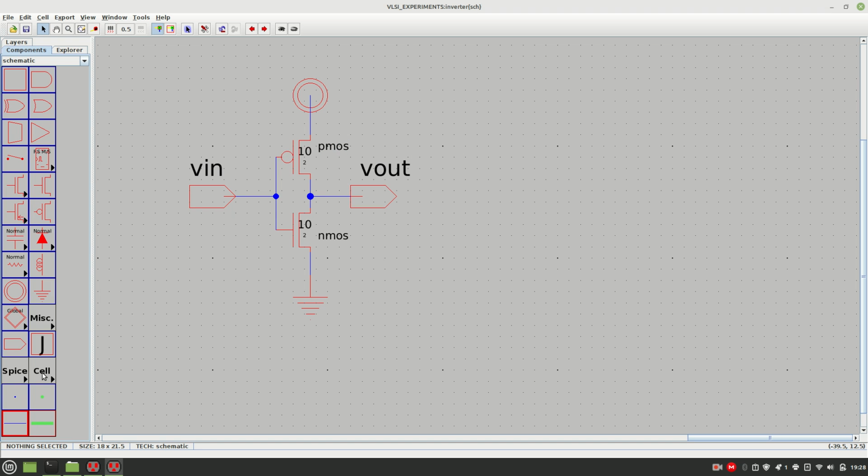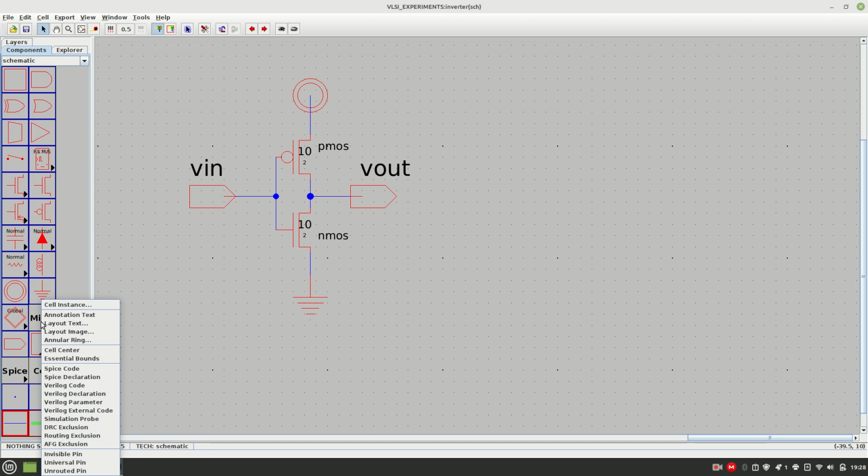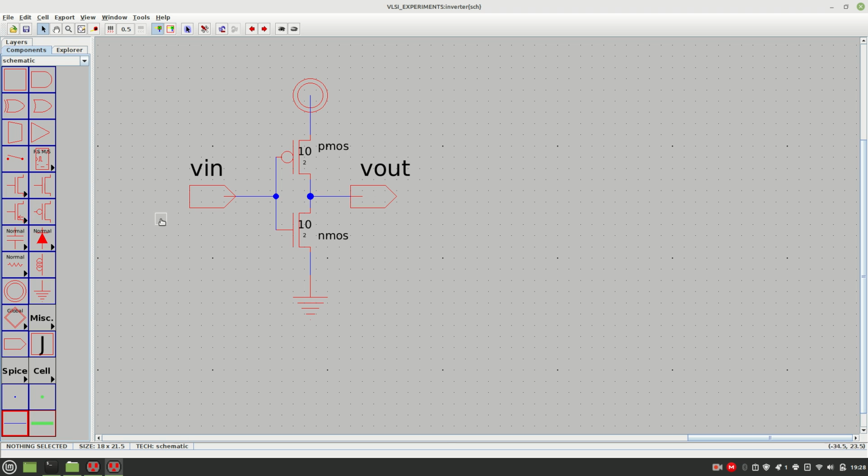So for that, go to the spice. Here is the spice, right? No, not the spice, go to MISC, and here we can have the spice code. Click on the spice code and click somewhere here. So this will display like this. Just click on this and press Ctrl I.